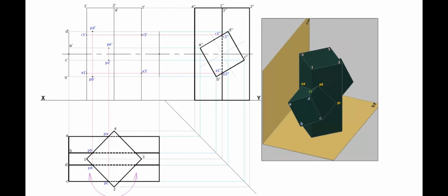Mark the intersection points of horizontal longer edges, in the plan, at the right-hand side also: QA, QB, QC, and QD, at the right-hand side. Project these points to the elevation. Find out the corresponding points in the elevation: QD dash, QA dash, QC dash, and QB dash.